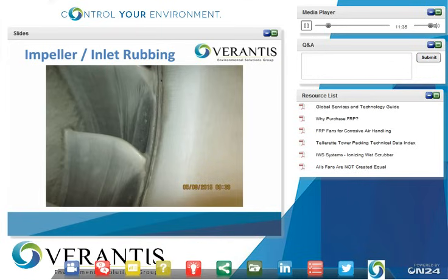This slide shows an impeller that has contacted the inlet cone here, and you can see where it has rubbed. What normally happens with that is something has moved, whether bolts on the housing or mounting it to the base have loosened up and let it shift, or, in the case of this fan, it had a bearing failure. When the bearing fails and you have a belt drive unit, the bearing is pulled off to one side, which in turn moves the impeller closer to the inlet cone, causing the rubbing you see in this area.